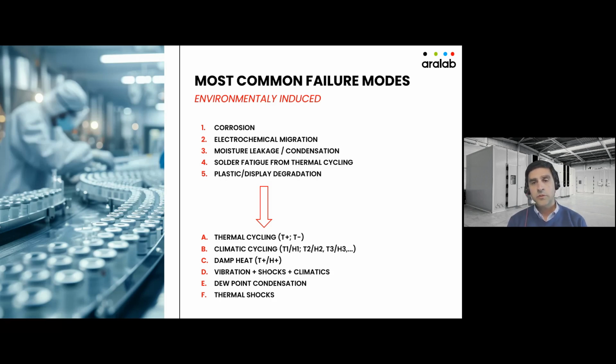And then we start going into more, let's say, demanding tests. One is vibration plus shocks plus climatics. So it's exactly what I've been presenting, but adding sine vibration, so a frequency that is defined by the users, or a set of frequencies, or a certain pattern of vibration, and sudden shocks.